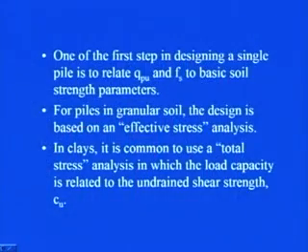So, in that case the design is based on effective stress analysis. That means that all the stresses that you will be taking, let us say overburden stress, you will be taking as effective ones. In clays, it is common to use a total stress analysis in which the load capacity is related to undrained shear strength. So, you see what exactly is the difference between the granular soil and the analysis in clays.